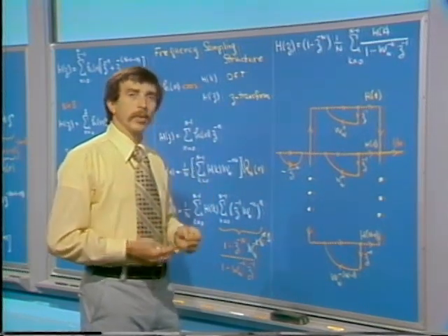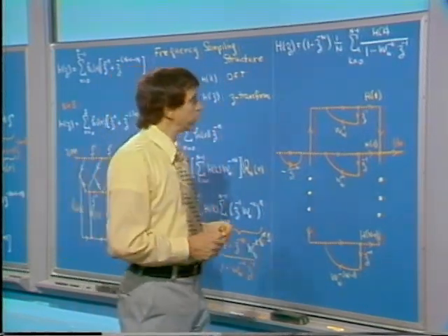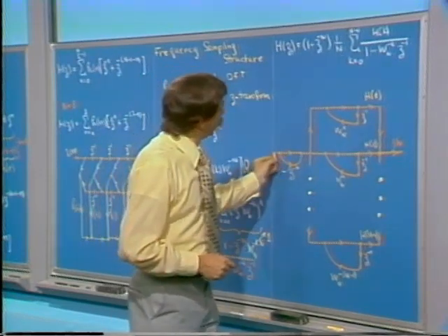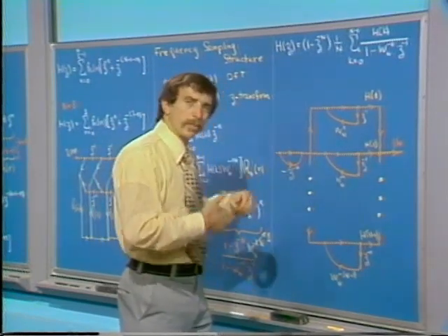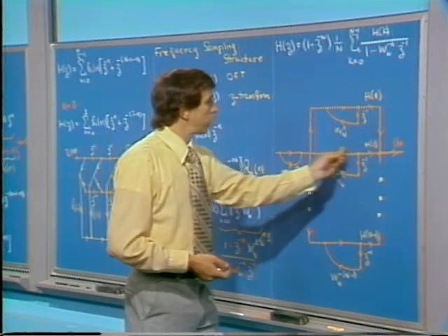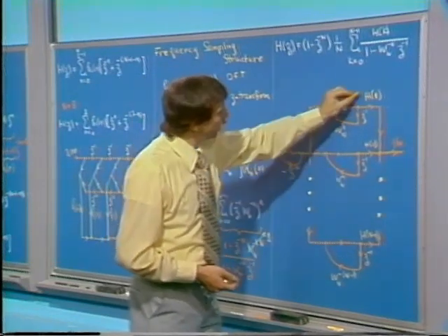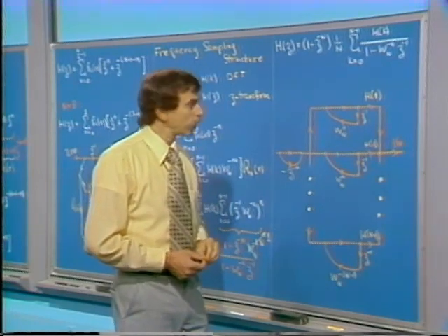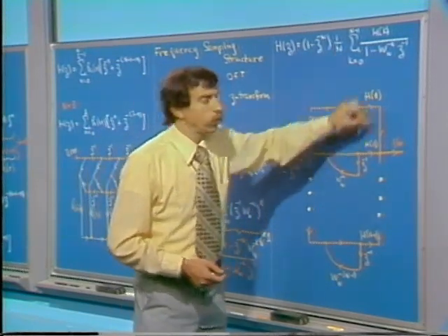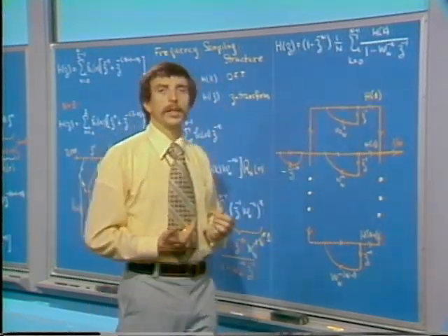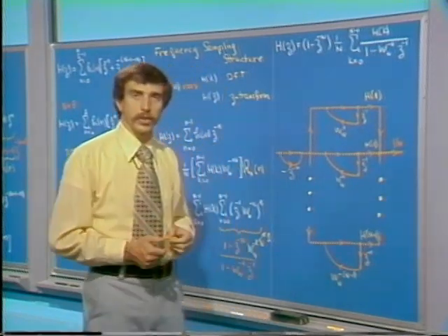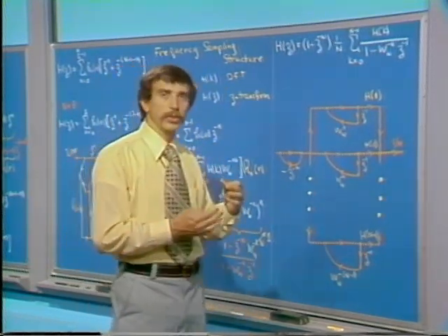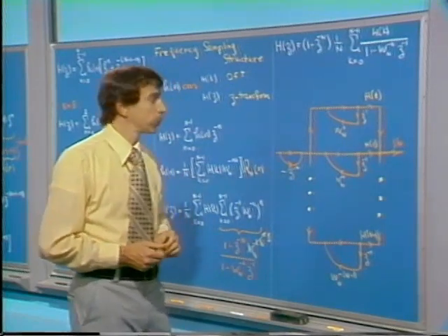Consequently, if I were to implement a large number of filters simultaneously, I can use in common for all of those systems the part of this structure from the input to the output of the poles, and then simply draw off those outputs, multiply by the required frequency samples, sum the outputs, and that implements the filter.